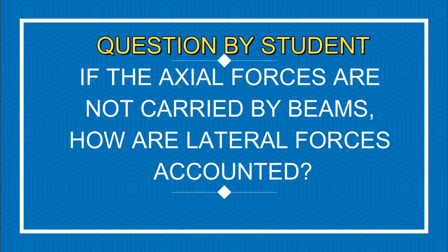His question is that beams do not have any axial force, so where does the axial force go? Let's say we are applying some force there. What element is absorbing the axial force? Let's say the earthquake forces are there and we have applied them at the joints. Essentially, where are they going? They are not going into the beam. Column, okay, but at the floor level they will not go to the column automatically. Basically they will come as axial force in the slab.